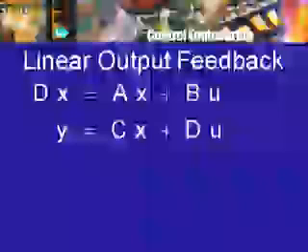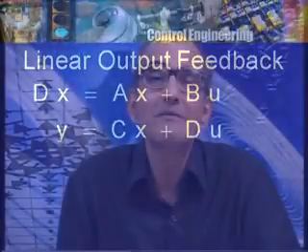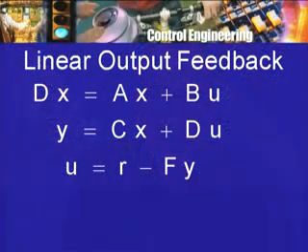And of course, continuing the earlier idea of feedback, the error detector or the difference device and so on, I can now think of building up my u from the reference input r, from which I subtract not F acting on x, but F multiplying y. So, u is equal to r minus F y.